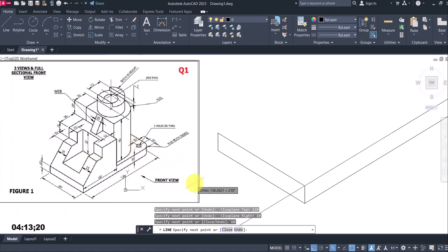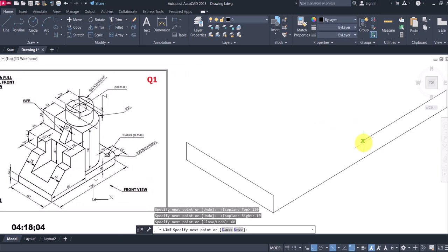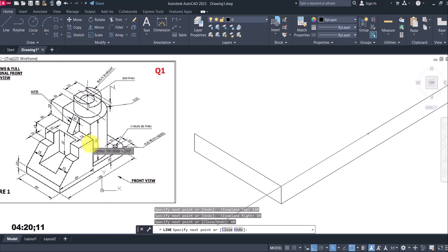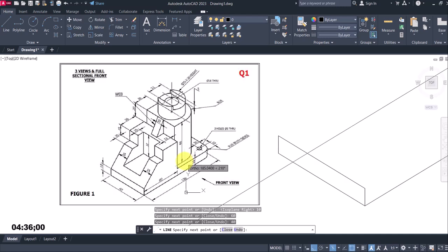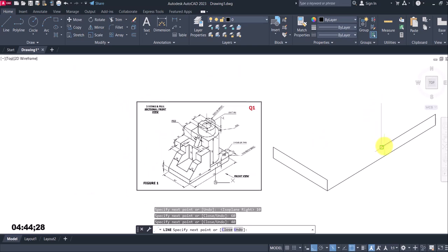What's the distance from here to here? Okay, now at this point, this distance is 60 minus 20. From this base here, 60 takes it to this top, then 20 down. So this height is 40. Check your dimension properly. You would agree with me that this height is 40. So how do I get it? 60 from this base to this top, then 20 here, step it down to this. So this height I need is 40. So I've been able to draw that 40.